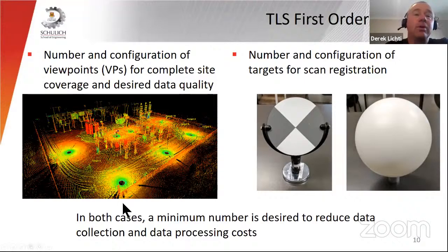And you can see the viewpoints indicated by those. There are 7 actually black circles. A few of them are easier to see. And those are basically the shadows beneath the instrument, the data holes. And they're surrounded by this green ring, if you will. And so the point cloud is colored according to laser return intensity. That's why they have that color.